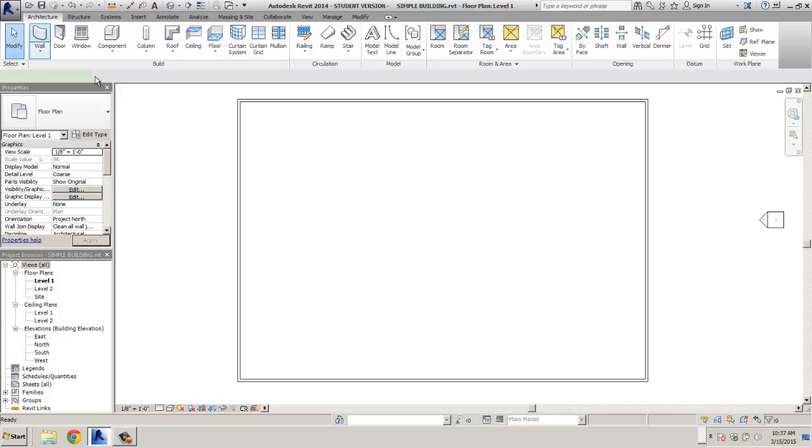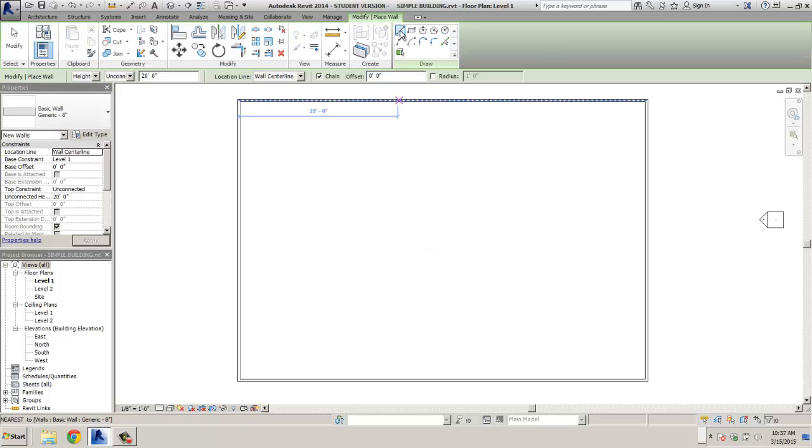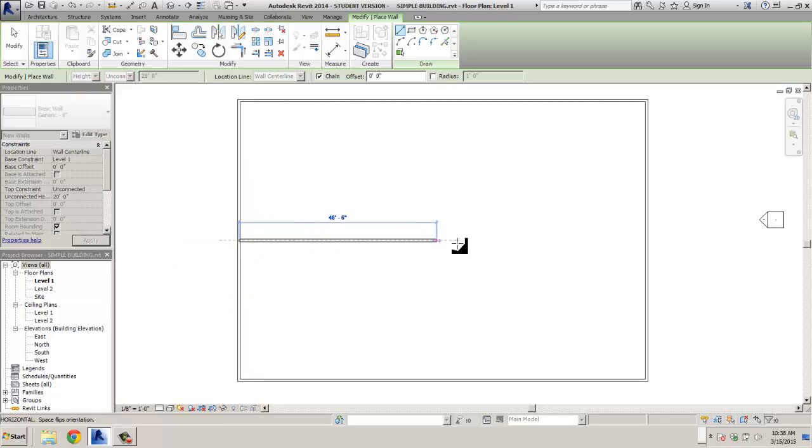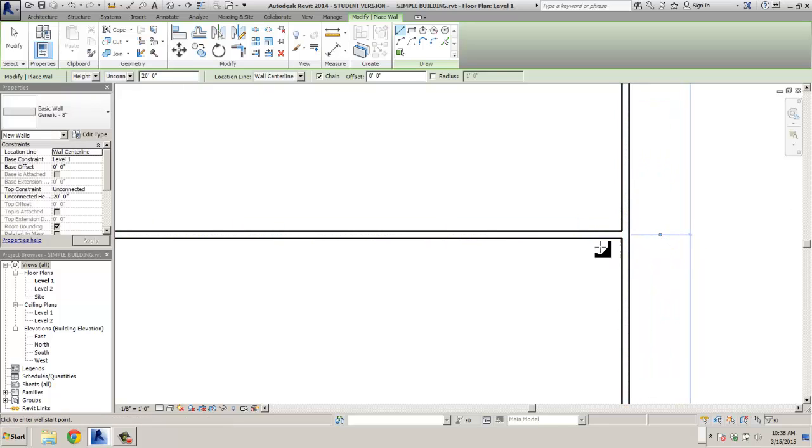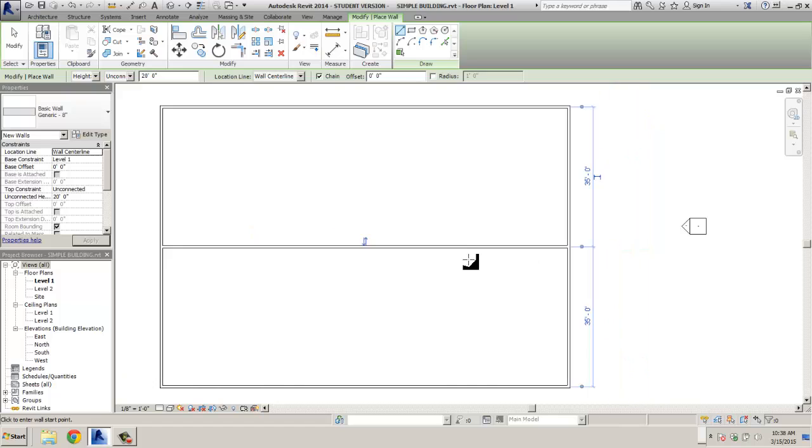So we'll go to our wall tool, select the line element. You come down here, you'll see that you get that triangular shape just like we did in AutoCAD. There's a midpoint. Just left click, bring it all the way over till the other midpoint. You'll notice it automatically heals the edges when it comes into that.